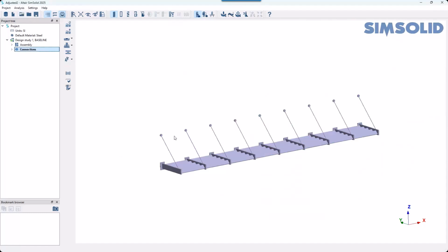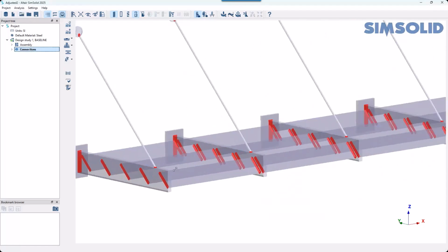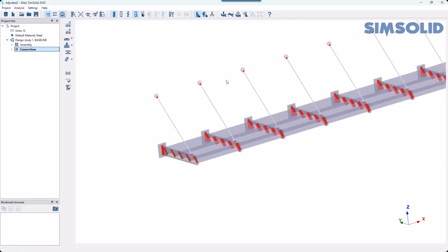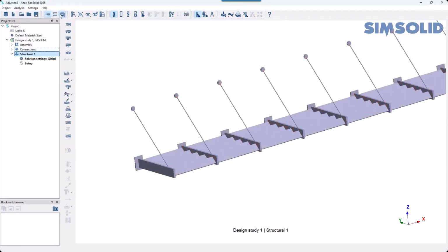I'm going to click the OK button now, and you can see really quickly it flashed on screen to show me that it had generated some connections, but I can actually view those here. If I right click and go to Show All, I can see all these different red colorings representing the bonded connections between the louvers and the horizontal cantilevers, as well as the base plates and the hung supports that we see up there. Now I can also set up my analysis. So I could say structural linear, perhaps. And I can go in and say, oh, I want to define an immovable support.